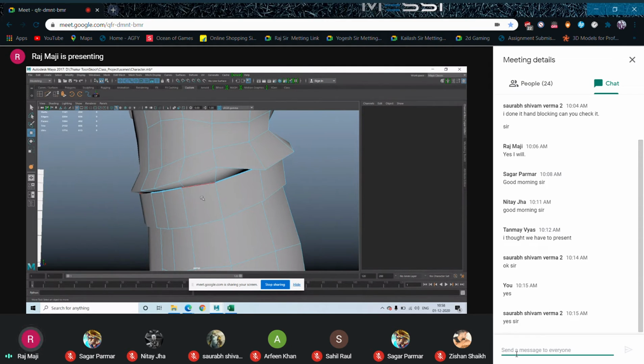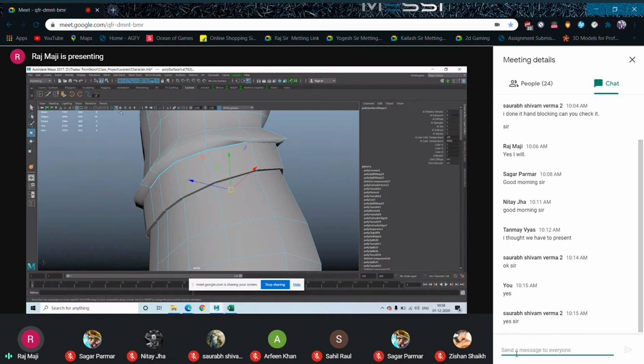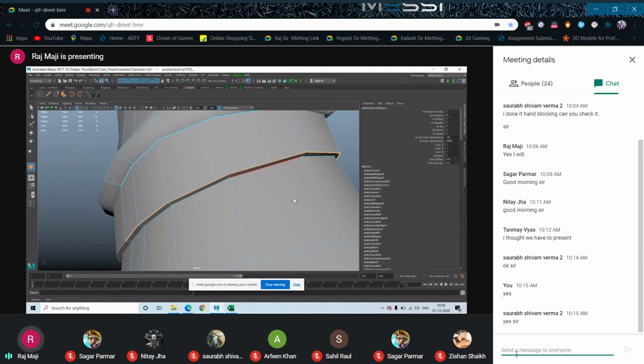So how much you will drag, middle mouse drag, that much sharp it will become. So the same thing I'm going to do over here. Let's check once again. Mesh tool, crease. It is written drag middle mouse button to add value in the crease. So middle mouse just dragging, and how much thickness you are getting, that much crease it is.